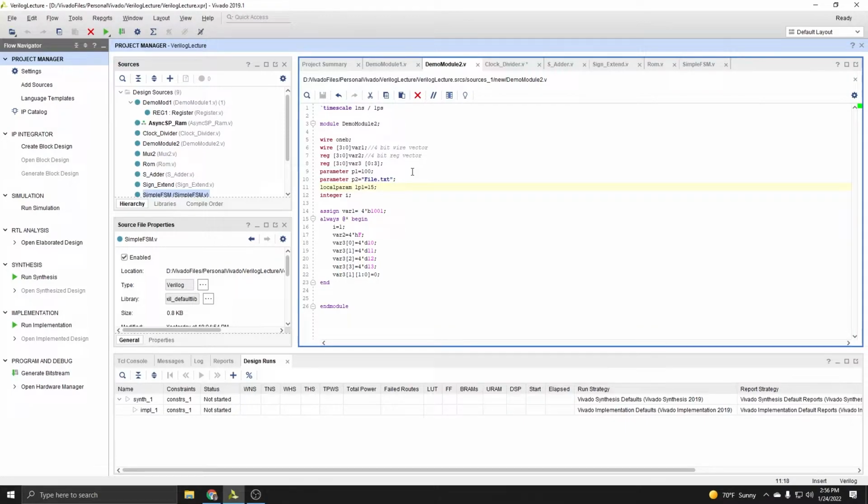They are more useful in the actual testing and test bench portion of working with your Verilog modules, because you can use them for things like loops, so that when you're running your tests, you don't have to have a test bench that's 1,000 lines of code. You can have a test bench that's a loop that loops 1,000 times and just uses i, like you would in a language like C. So I don't recommend you end up using integers in modules, though in some cases they can be synthesizable. Like I said, I don't recommend you use them that way. Just use them for testing and keep using vectors and specifying the sizes like you normally would in modules.